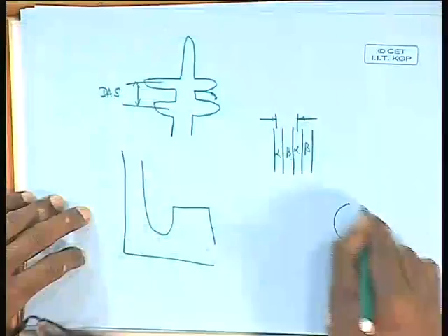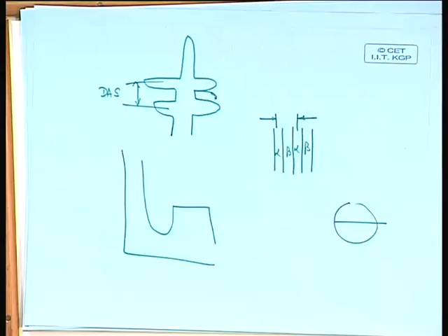After the particle has really solidified, what you do is cut the particle, look at the microstructure, and you can identify what the microstructure is, what the dendritic spacing is, or what the interlamellar spacing is, and from that you correlate it to the undercooling. Different types of particles, different sizes of particles will have different undercoolings and different microstructures. So ultimately you correlate the microstructure to the undercooling, and to the cooling rate if people do fast cooling experiments.